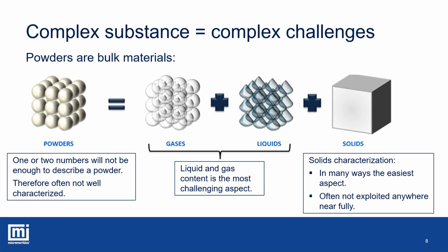Liquids are a sticking point with powders, not least of which when they get damp and clumpy. But seriously, these often present some of the most significant processing issues, as having the right amount of the right liquid correctly distributed through a product can often be the difference between one that works and one that doesn't. The quantity present is relatively easy to measure with techniques like Karl Fischer or GC headspace, but this does not take into account how the liquid is distributed through the powder.